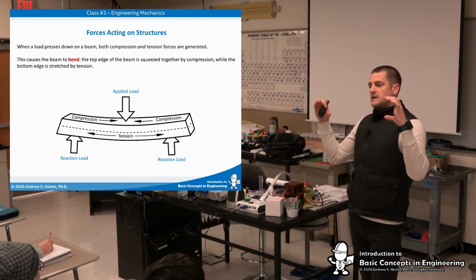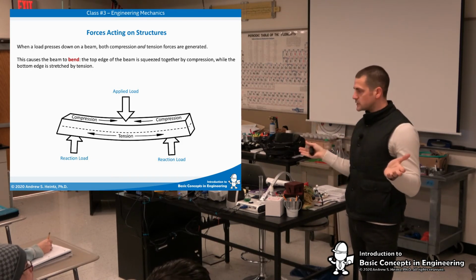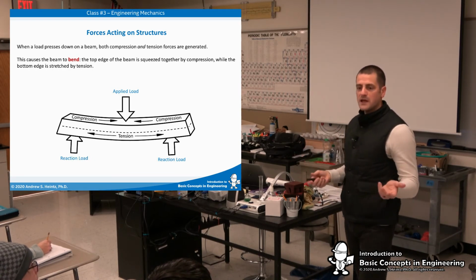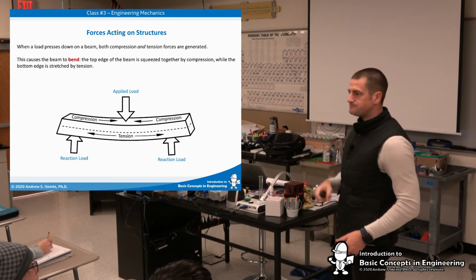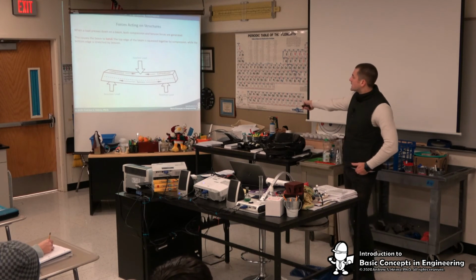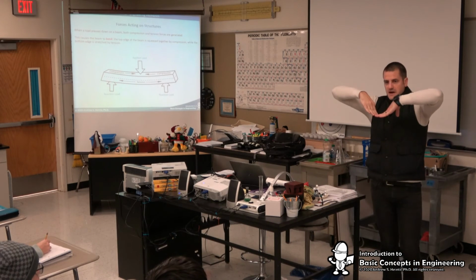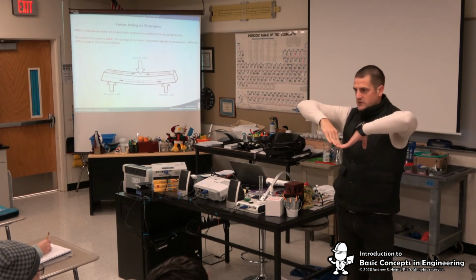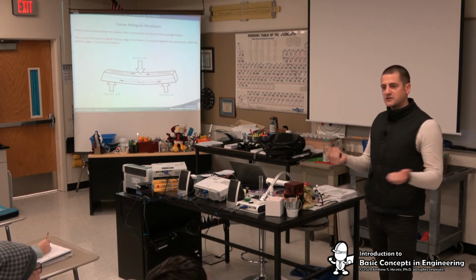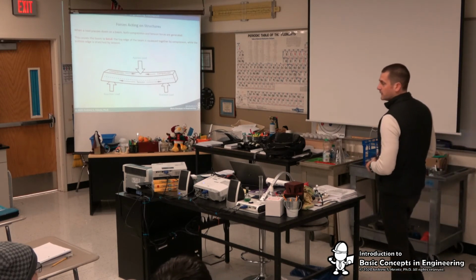If I just have one member within that bridge, let's just say we have a log bridge. Make it super easy. We took a 2x4, we laid it across the creek because we had to get to school, right? As you're walking over that, we all know that it bends. Bending is a super cool case of material deformation because the top of that material is actually under compression. Because as you think about it, the top is being pressed onto each other. But the bottom, because it gets longer, the material itself is actually under tension. It's actually starting to tear itself apart.